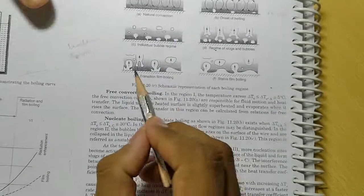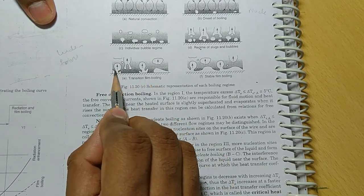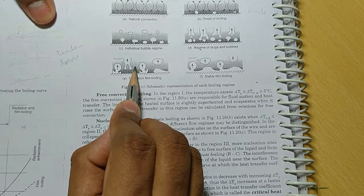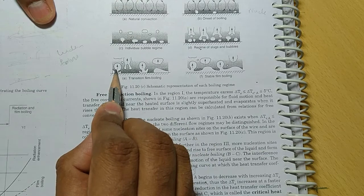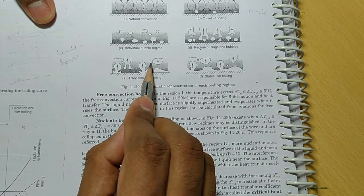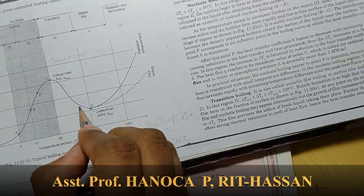The reason is that, here you can see, the formation of bubbles covers the surfaces, and this reduces the heat transfer. This reduces the Q between the fluid and the surface, because of the formation of these bubbles. The bubble formation or slug formation avoids the contact of water with the surfaces. So that is why the heat flux reduces.